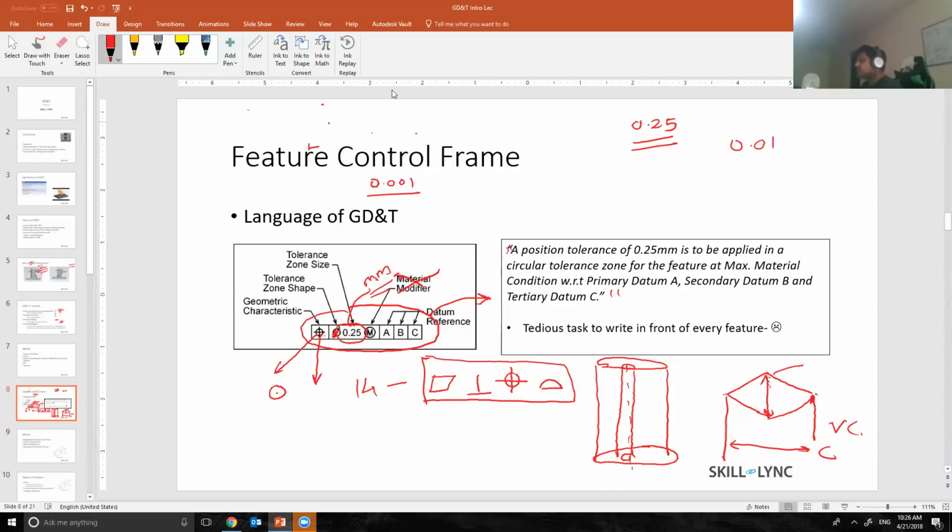But in general, let's say any machining flatness has 0.25 millimeter. A position tolerance generally is 0.5 to 1 millimeter if it's a drilled part, and the profile can vary between 1 to 2 millimeter. And this is for an engine mount which only has functional aspect. There is no visual aspect to it.